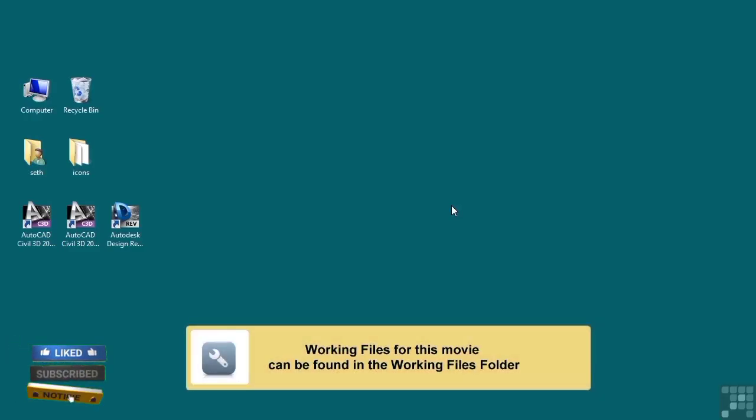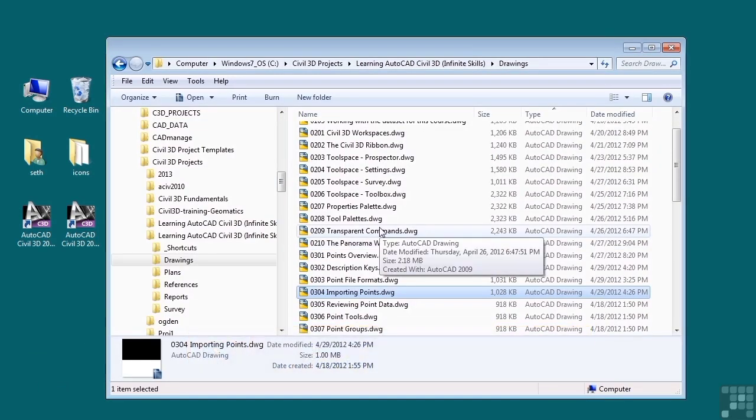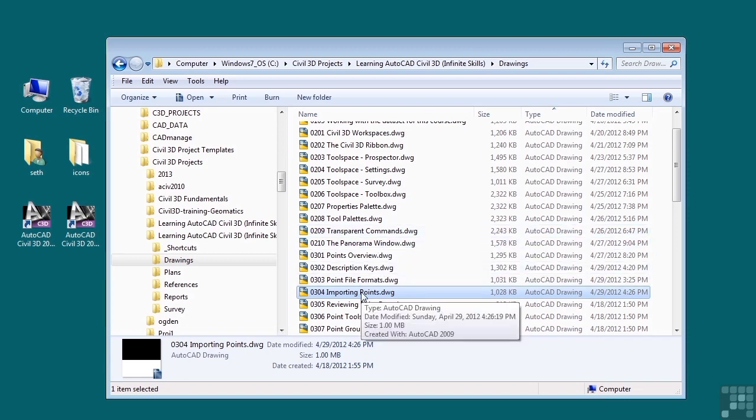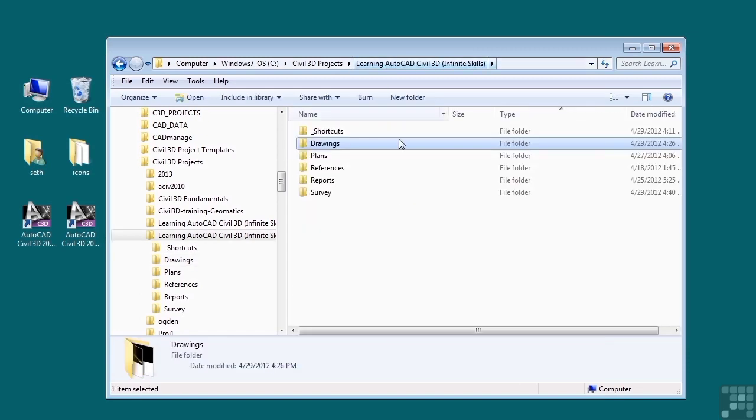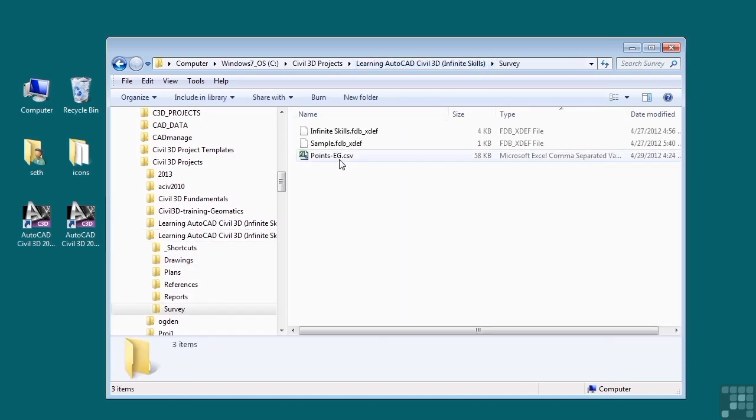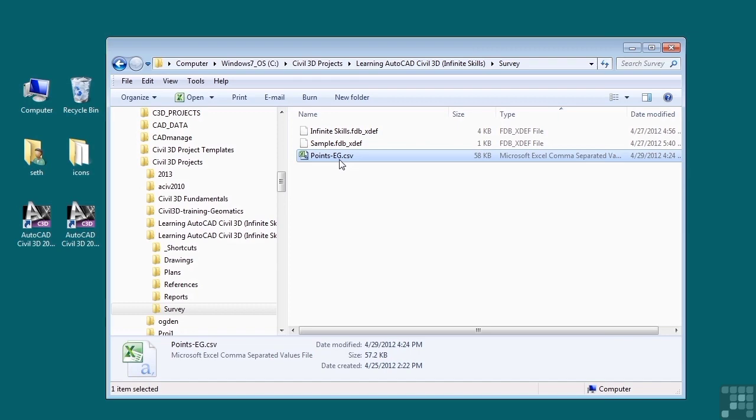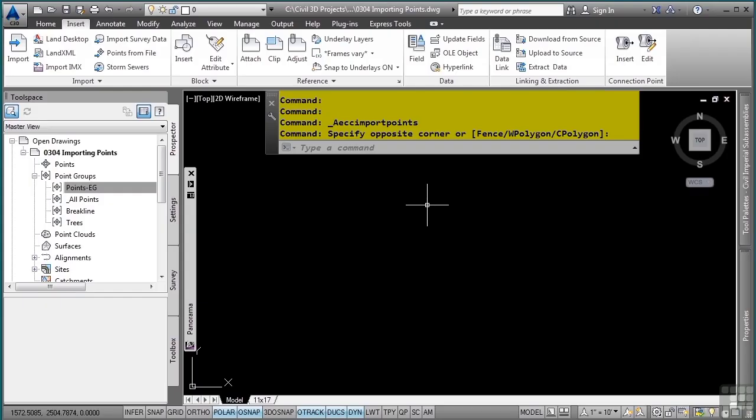In this video, we will discuss importing points. If you would like to follow along with the video, please open the file 0304 importingpoints.dwg located in the training folder as discussed in the Working with this Dataset video. In addition to this file, we will also use a point file located in the training folder, survey subfolder, points-eg.csv. Civil 3D enables you to import many types of files based on various point file formats.